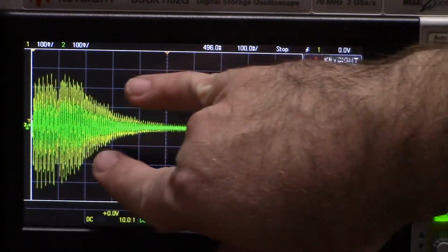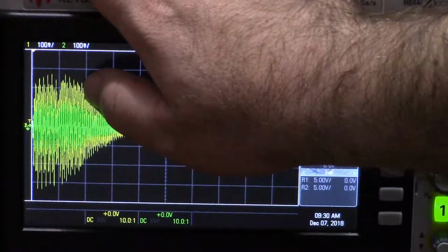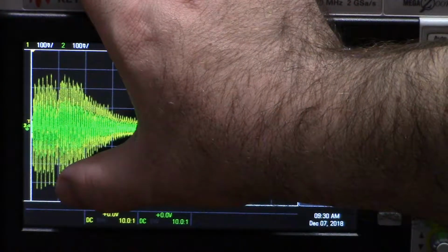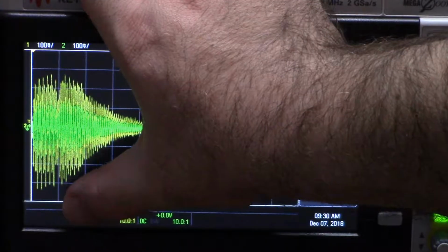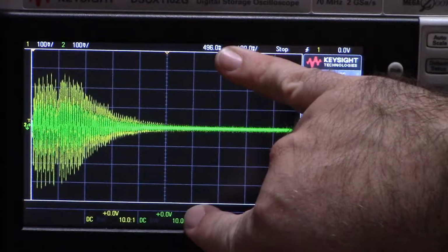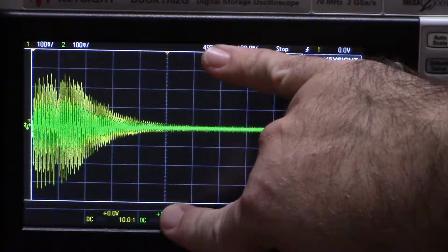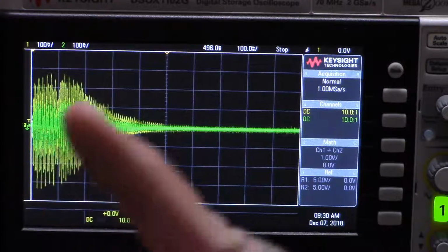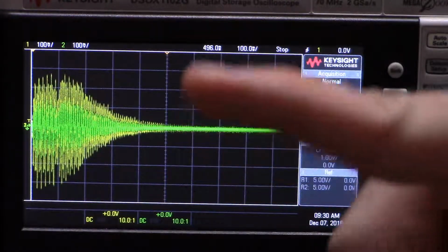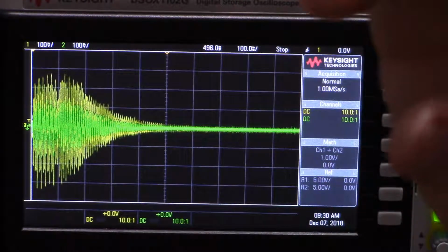Generally, I'm seeing signals that go to about 250 millivolts, a smidge over, maybe 275, but this one does dip down to about 350. So if I were engineering something, I would say, well, why not just make it 1 volt peak to peak? That'll definitely include all these signals, and it's nice and safe. Because there's another factor here. This is the maximum output volume, but do we know that it's the maximum output audio signal?